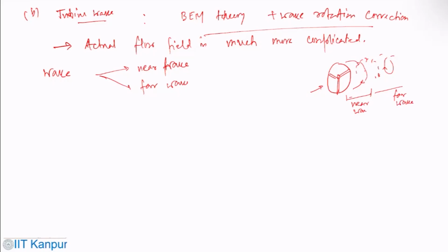Okay. So the difference between the near and far wake is a function of the spatial distribution and intensity of the turbulence in the flow field. The near wake, which is close to the turbine downstream location, will have more impact on the flow field and more fluctuations, but far away it could be a little bit calmer and the effect of turbulent intensity gets reduced.